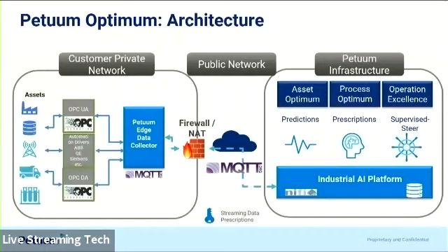Our experience has been, doing different types of implementations, we work in the cloud. We can get this data using our edge data collector, using OPC from the DCS. So the DCS goes into the edge data collector via OPC, then from the edge data collector to a platform using MQTT. And then we can read the data and write back the results. This is one of the ways that we can deploy it. The models are trained in the cloud. They can be retrained and redeployed with a minimal installation on the customer side.